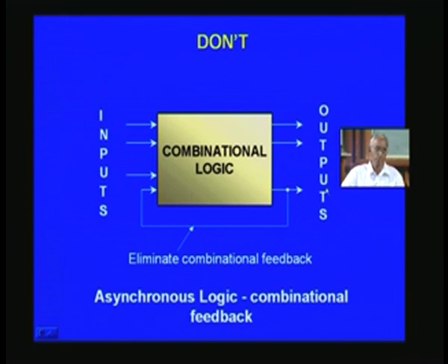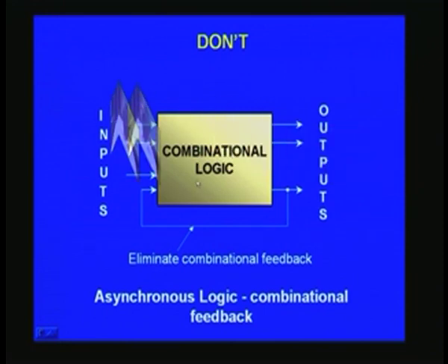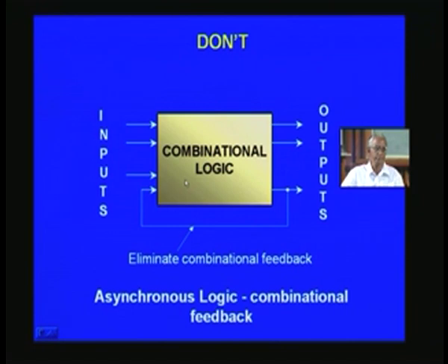When you use the synthesis tool, this is not permitted. It will give a warning or error message as such, and perhaps you can veto that and go along, but ultimately you will end up messing the whole design as such, for the simple reason that your design will not work on the ASIC or FPGA that you have ultimately done, and that's the reason why we should stick to these RTL coding guidelines as such, without which you won't get a working chip as such.